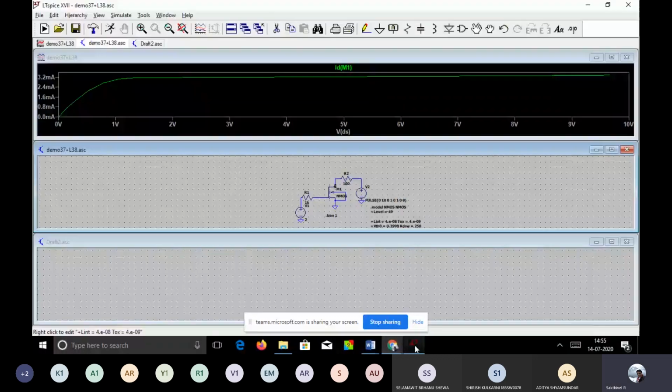Okay, fine. That's all. Now, this is for a single value of this VGS. For different values of VDS along the x-axis, you get a current flowing from 0, then it comes to saturation. This is what you call the device being in different regions. So somewhere around 0, there is no current, that is cut off. Then after that you get a current. This is what you call linear. Up to this point it is linear. After that the current becomes almost stable.